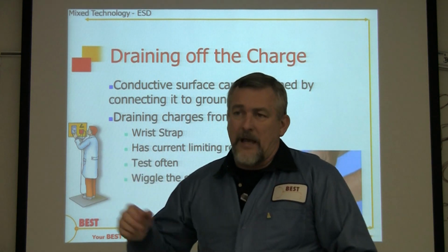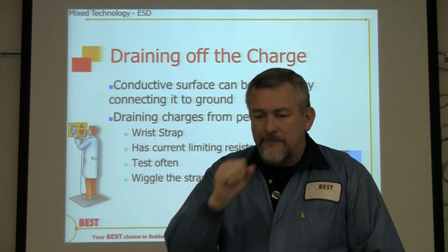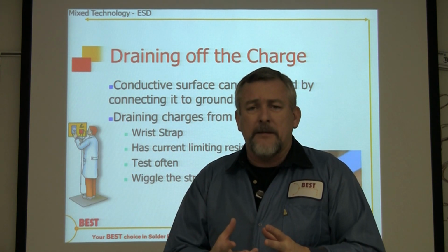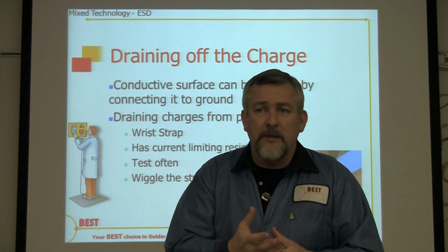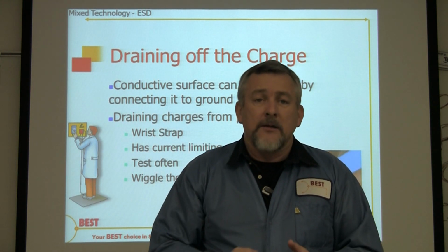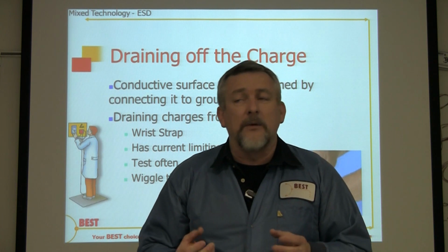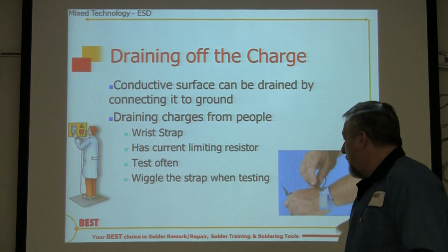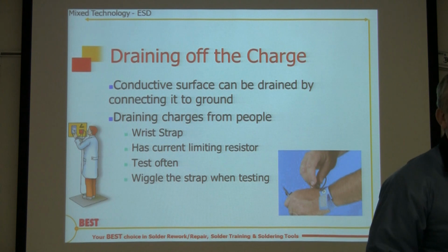And not a lot of companies do this, but there are companies out there where, to get into work, you have to do this. To get into that workspace like I just talked about, you have to be ESD safe. So these are one of their fail-safe ways to do it. Okay? Wiggle the wrist strap when testing. Again, like I said, it could be intermittent.